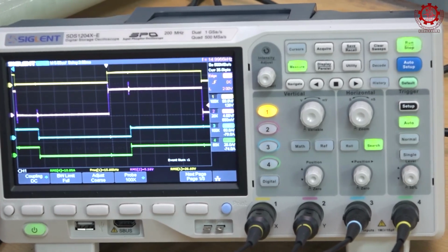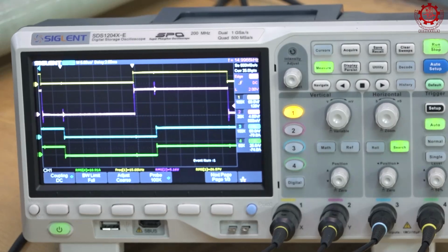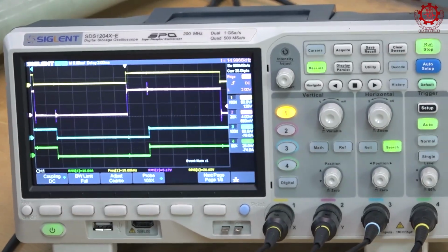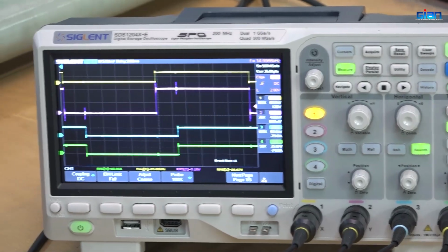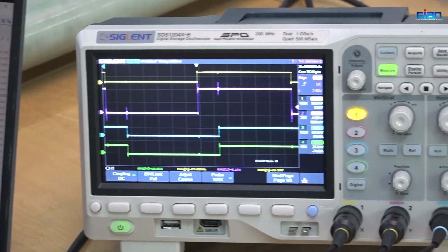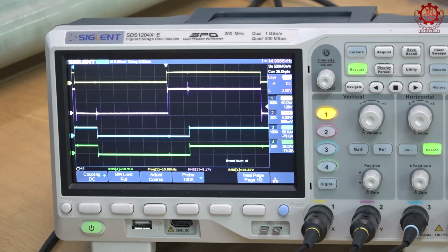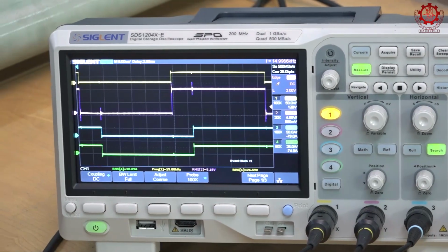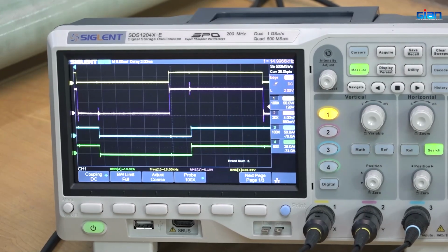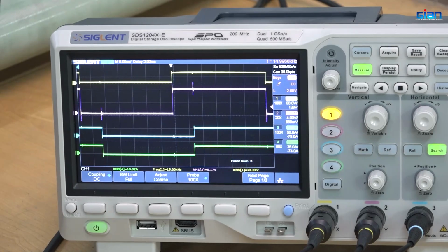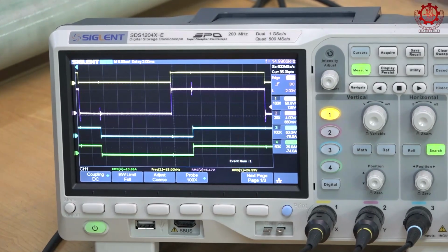Here we can't give the 40 degree phase shift directly in this program; we have to convert it into a digital value. So for 40 degrees, the digital value is 0511. It should be in hexadecimal. EPWM is a 16-bit register, so we have to give it in hexadecimal mode. So I gave 0511. The 40 degrees is converted to digital as 0511.